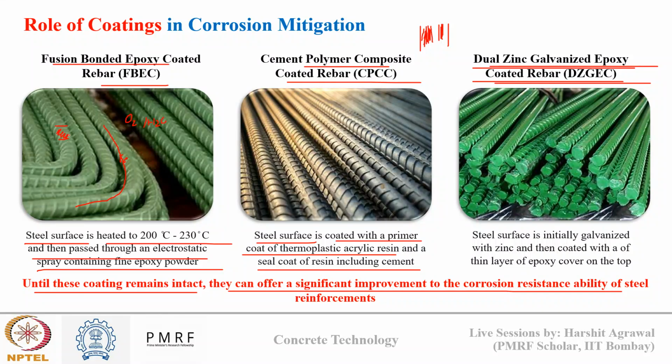So that's why the use of coated rebar needs utmost care for effective application. A damaged coated rebar is worse than a non-coated rebar. So protecting these rebars against damage before being used in concreting is very important.